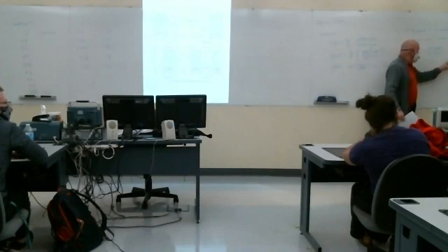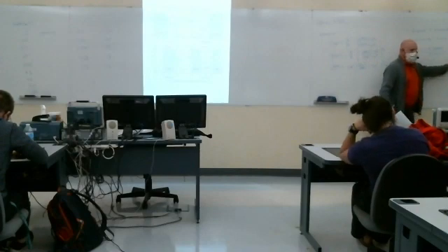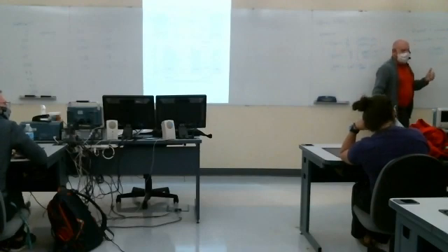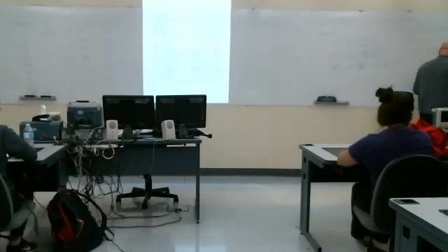At very high frequencies, when these terms dominate, we'll have omega over 8,000 divided by omega over 1,000, that would be 1/8. So at very high frequencies, the gain is actually 1/8 of 10. So it looks like it's going to be a low pass filter.